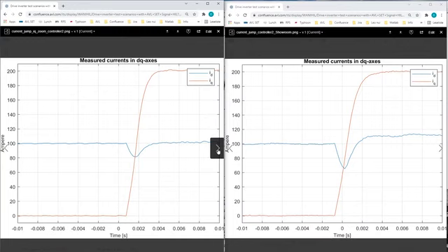On the other hand, we can see a small difference in the results of the two systems. The D current in the low voltage system remains stable around its 100 ampere set point, whereas there is a small offset between the set point and the actual value of the D current in the power HIL system. This current offset shows us that although being a powerful tool to design and optimize the inverter controller, which accelerates the inverter development process, there are still effects which are not emulated by the low voltage HIL system. Therefore, the power HIL presents an essential tool for inverter testing.